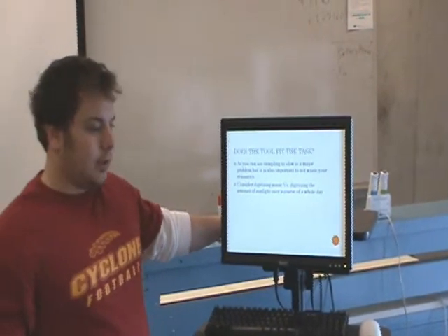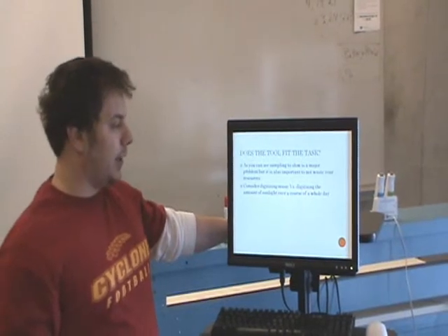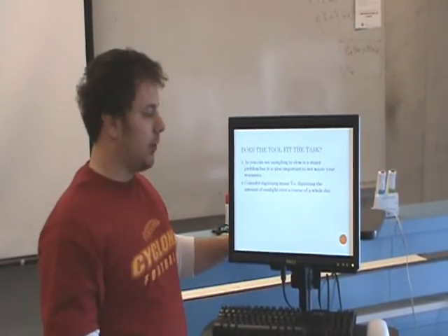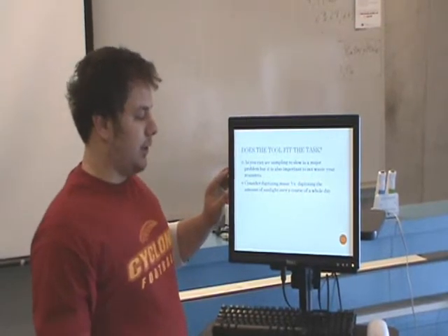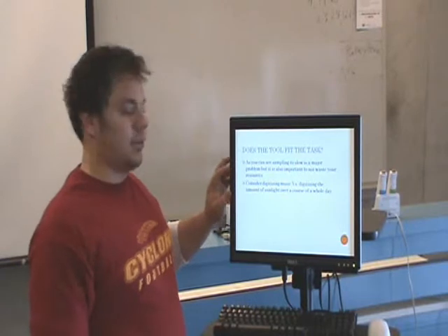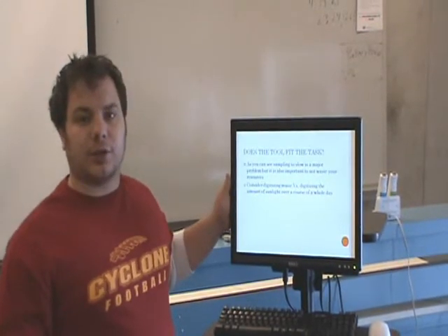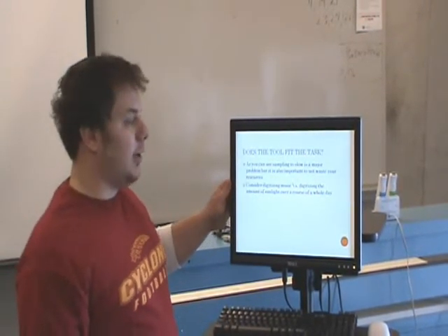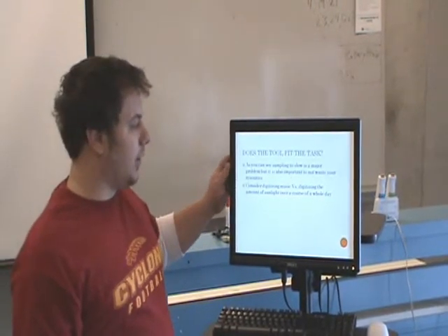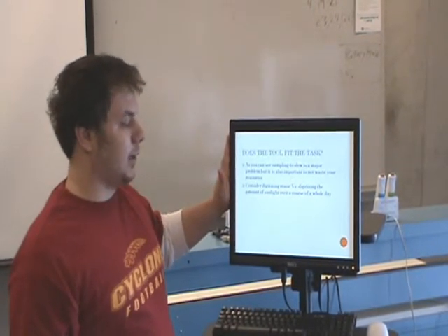Another thing, the higher the sampling rate, the more expensive your chip's going to be. So if you're going to measure something slow, like for instance, for a microcontroller, most music is considered slow, you could use a normal microcontroller analog to digital converter for that. If you're measuring something in the high kilohertz to low megahertz range, you're going to want something a little better.